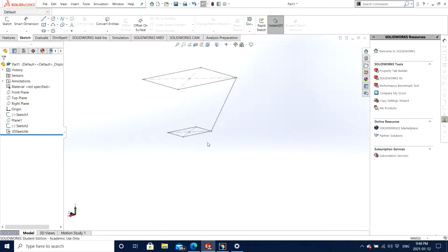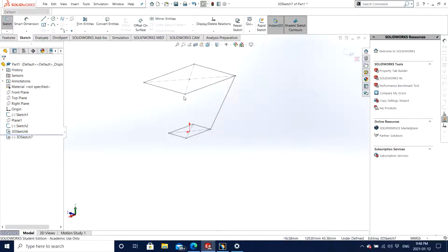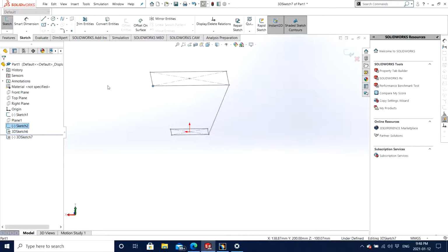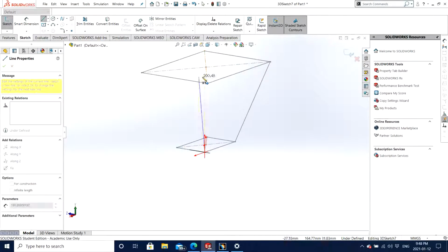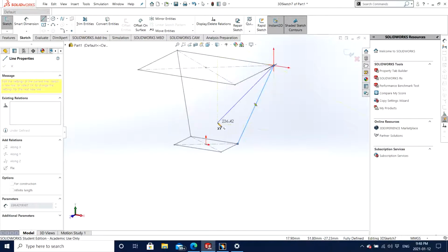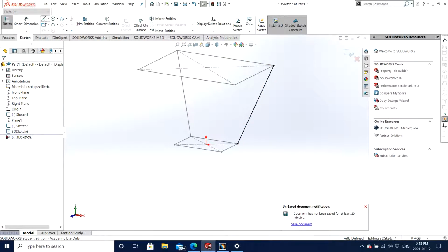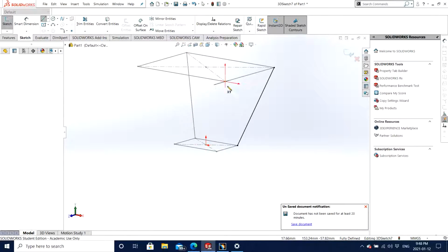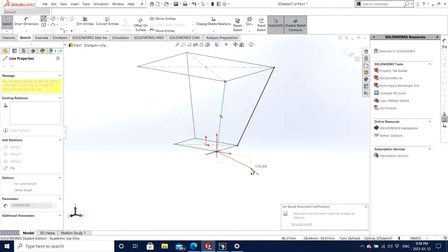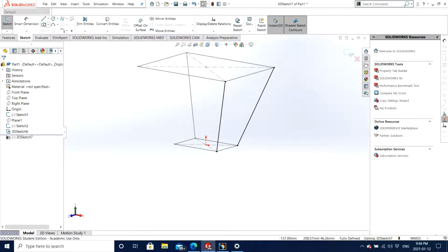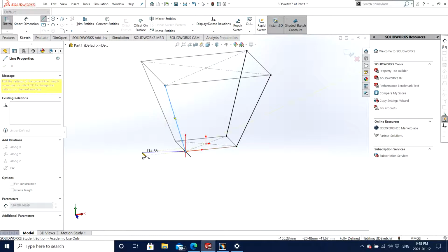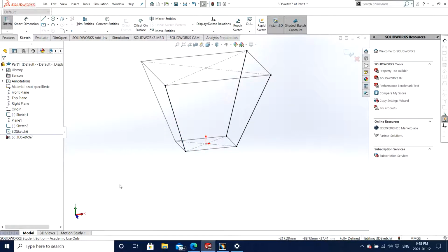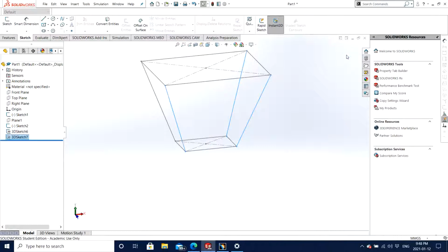So in this case we are going to use a 3D sketch, and similarly we can make 3 other simple lines. We don't need to be too fancy. Simple right here. Click on this point, click on this point. It's always recommended to use guiding curves, although this part can simply be made without guiding curves if needed, but that's just my recommendation.